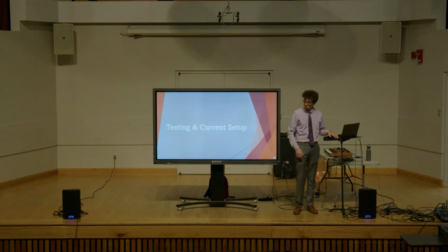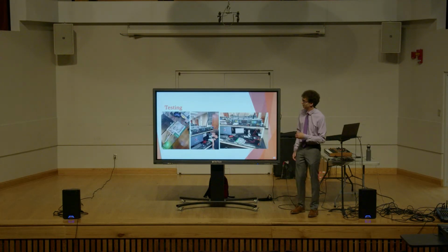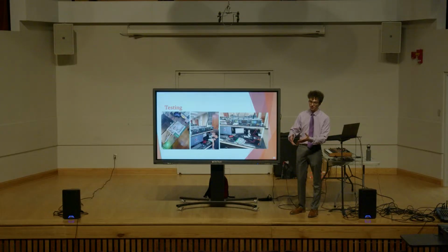So let's take a little look at a couple of testing setups that I've had for this project. On the left, you can see at my desk at home, I'm using the power supply PCB, which I designed, to suss out new stuff. And then setups in labs would often look like this, where I set up the circuit, I set up an audio interface for recording audio output from the circuit, run that into my computer. The computer is often hosting a code compiler, so I can write new code, update that, compile it, send it to the Pico to do something different. And then I'm also using power supplies and scopes to measure whatever I need to measure at any given point in time.